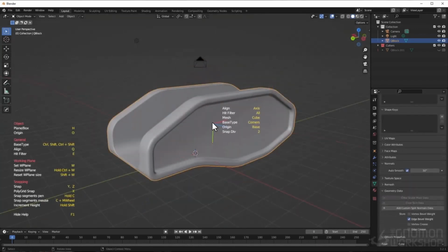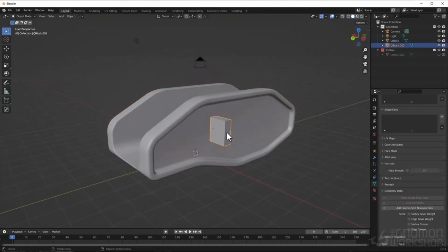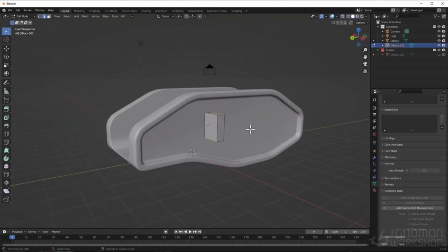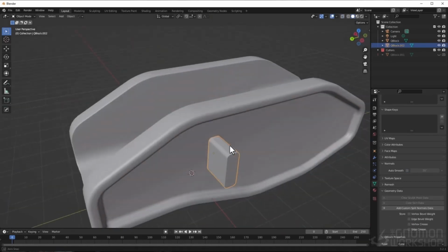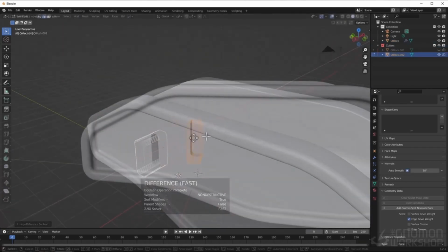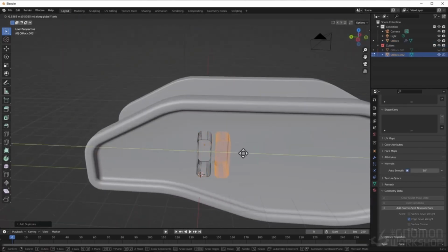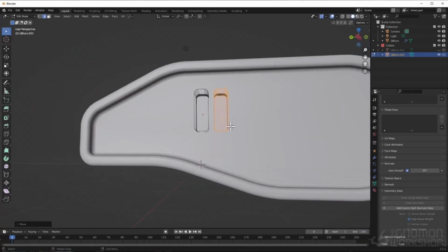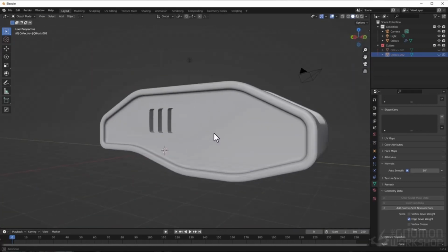When the overall shape is done, I'll then use the same process to add details here and there based on the photo reference. Same as before, creating a primitive with QBlocker and using HardOps to Boolean the shapes together. Here, I'm using Shift-D in edit mode to copy the shapes across inside of the object. I'm pressing H here to hide the cutter object so I can see the result more clearly.